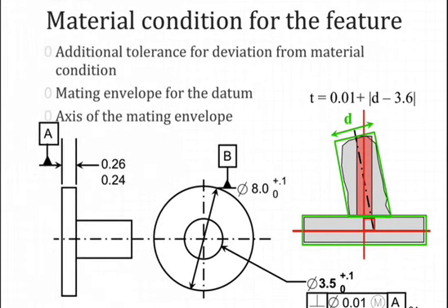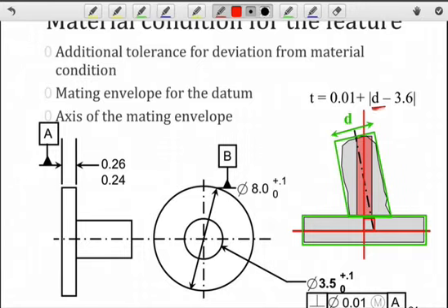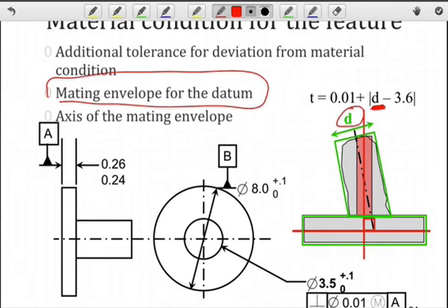And that's reflected, as we've done before, by adding in that deviation. So we have to measure the amount of deviation from material condition that's indicated by D here. And we do that by using the mating envelope, as you would expect, and I contract the smallest cylinder around this feature to determine what D is. Then I subtract the maximum material condition, which we can determine from the feature's dimensional tolerance. So my total width here is unknown until we actually make this part.